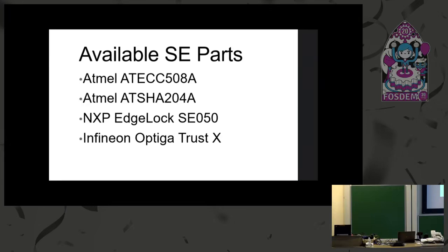I think the largest form factor is a QFN, so that's quad flat no-leads. All of the contacts are underneath the chip, so it makes it very difficult to use a typical heated-tip soldering iron. You need some reflow or hot air solder methods to be able to solder most of these. The Atmels that I listed here are much easier. They have, I think, SOIC, so you can see the legs of the chip.